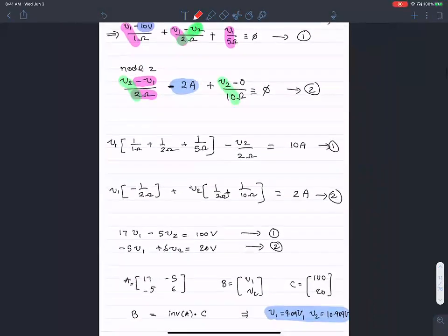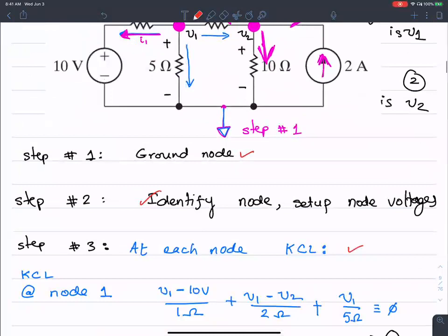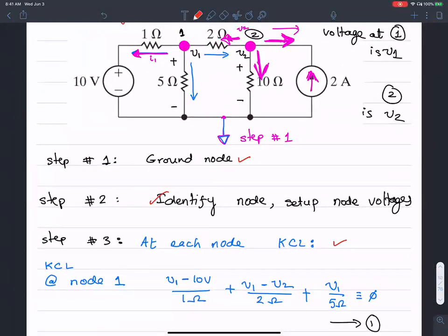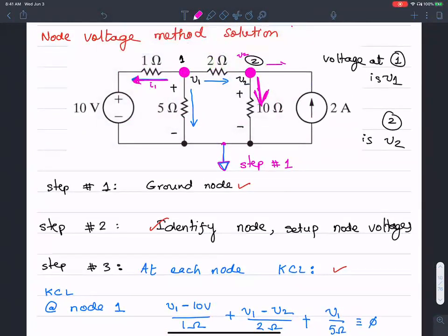Professor, can you explain? Sometimes on the homework, I get confused when they ask, for instance, the power at the current source 2A. And I saw some examples online using this way of using the node voltage source. Okay, so the idea is you want to look at the current. Here I have defined all the currents to be leaving a particular node, and I apply KCL at that node. So when it comes to calculating the power, all you have to do is find the voltage at that current source and multiply that with the current, V times I.